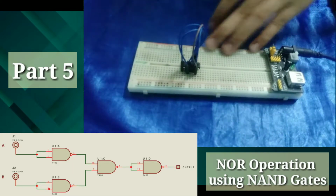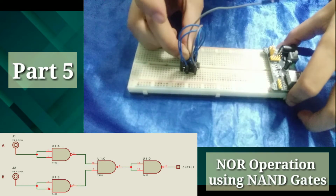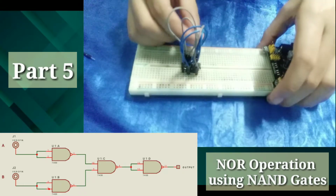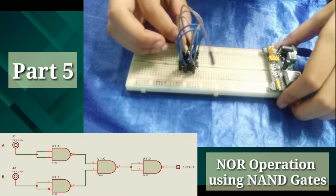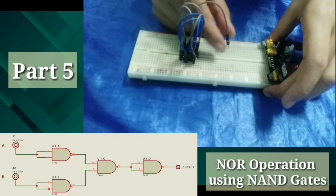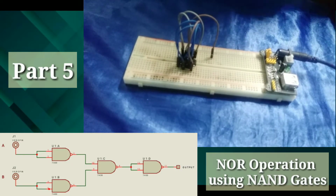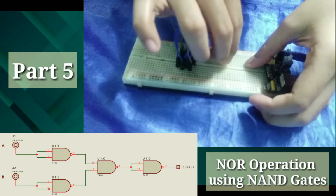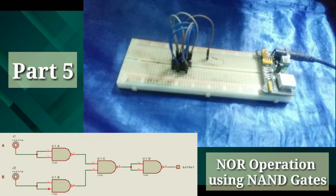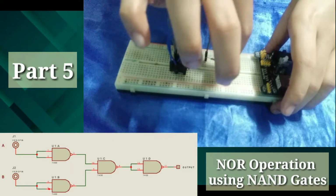So here it is. And pins number 12 and 13 are connected. And the connection of these two is connected to pin number 8. Our output will be connected to pin number 11. So let's connect it here, pin number 11. Then again, let's connect a 360 ohm resistor in series with our connecting wire. And then of course, don't forget your LED. That will serve as your output.